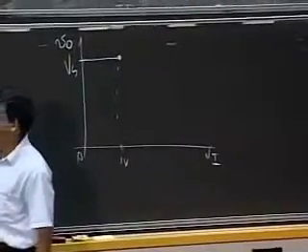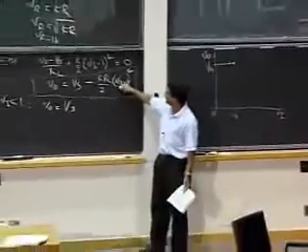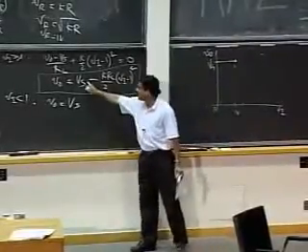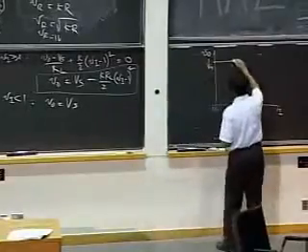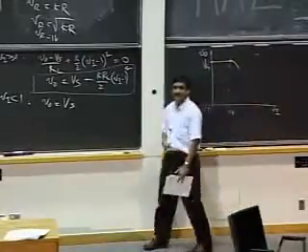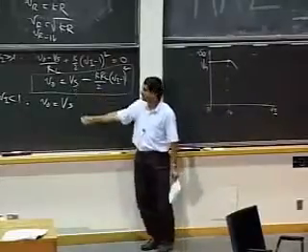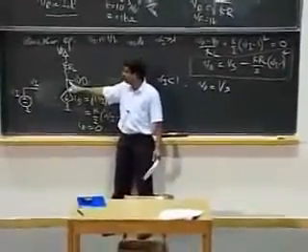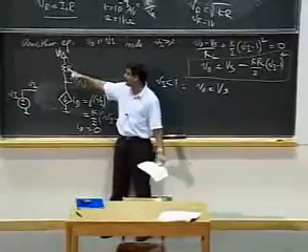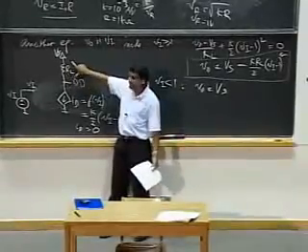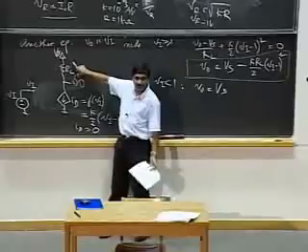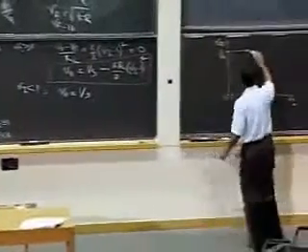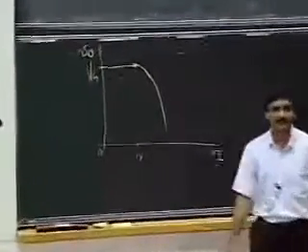Okay, phew. So I start off here. As Vi increases, what happens now? As Vi increases, this term here becomes increasingly negative, subtracting from Vs. So I get some behavior like this. V0 begins to drop, and it makes intuitive sense. As ID begins to increase, the voltage here will begin to drop because I'm drawing more and more current through RL. I'm dropping more and more across RL, so V0 begins to drop too. No big shakes here. So it looks something like this.